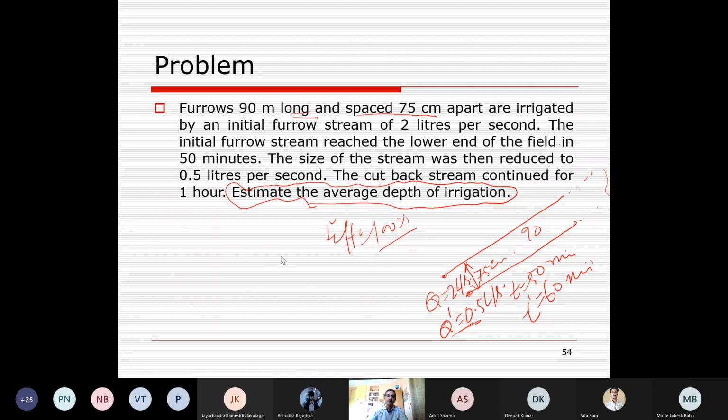Okay. So here we learned the surface irrigation methods. Uncontrolled flooding is usual, no problem because water limitation is not there, so you can flood the area. The remaining 3 methods are border, basin, and furrow. You learned about advantages, disadvantages, and different conditions because of soil characteristics, slope conditions, and crop requirements.